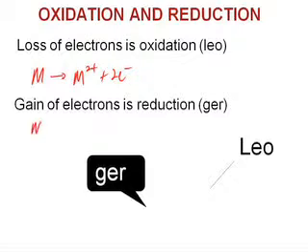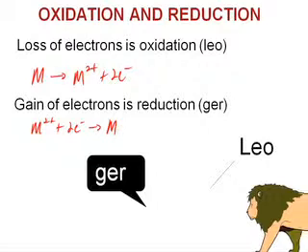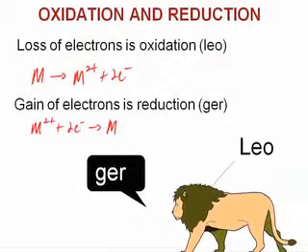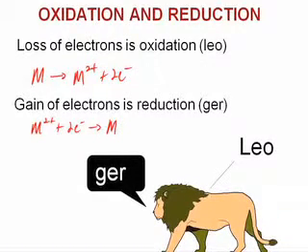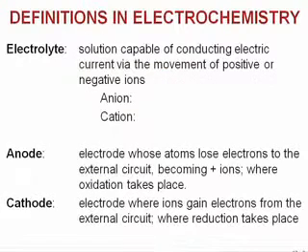So that would be the opposite of that. We could, in fact, plate out metal ions, or I showed you the reduction of H+ to form H2. Okay? So reduction is a gain of electrons. Oxidation is a loss of electrons. And here we have Leo the lion saying grr. Again, the idea is to remember we have an oxidation reaction and a reduction reaction. The two of them combine in a corrosion cell to form a total corrosion reaction. Leo the lion says grr.